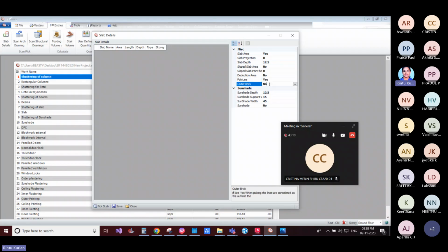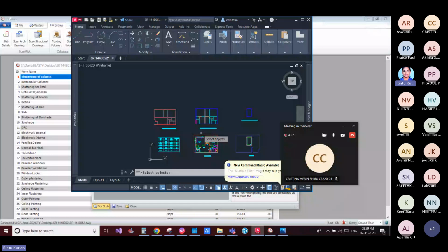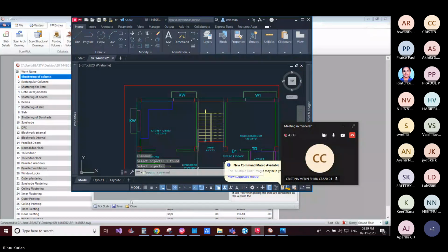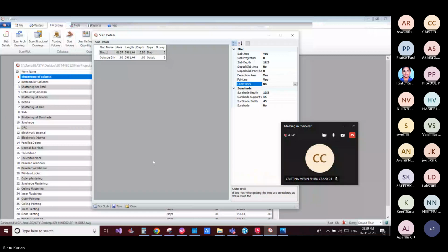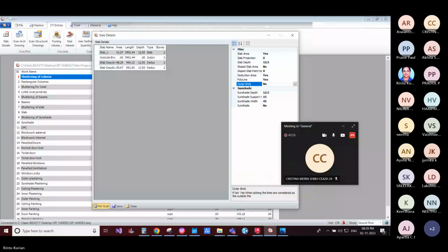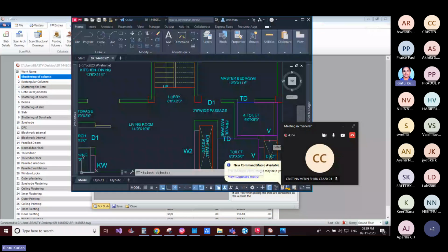Usually we draft this particular polyline for slab and reduction in the 0 layer. You can opt for any layer other than the layers we are using for beam, column, slab and other CAD utilities. Then go for the reduction part. Pick slab. Slab. Okay. Now the quantities have been entered.